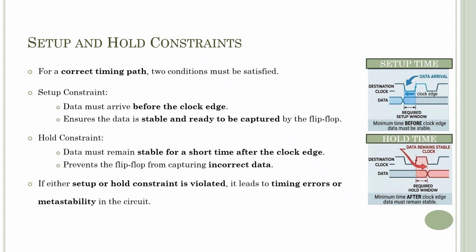So, in summary, setup ensures that the data arrives early enough before the clock edge, and hold ensures that the data remains stable long enough after the clock edge for reliable data capture.